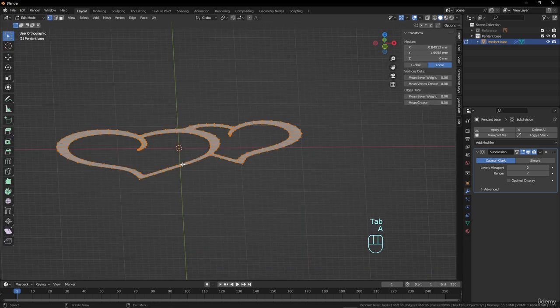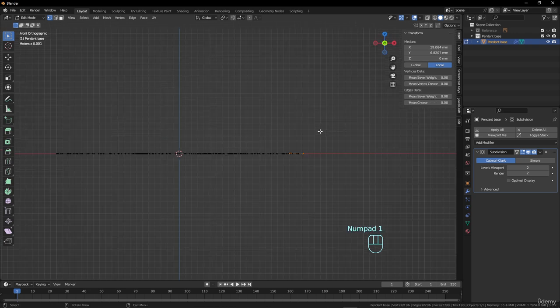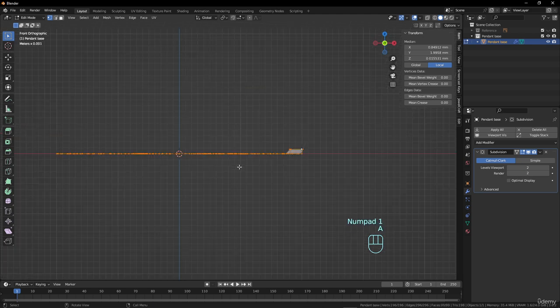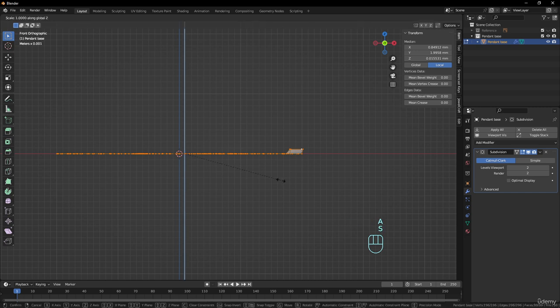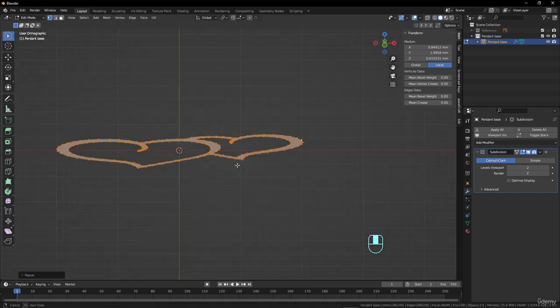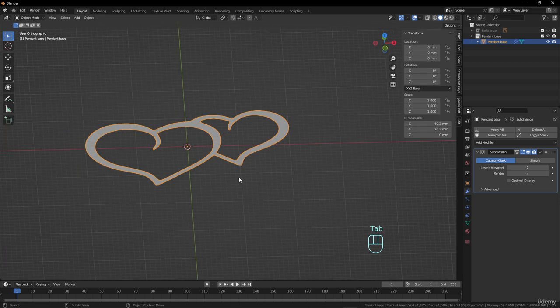If it's not flat, if for example there are some vertices there, who knows, and you make a bad extrusion, or you changed the view during the process of extruding, you'll have something like this. When you have this kind of problem, you press S Z 0 like that, and everything will be flat again. Okay, so now you have a design that is ready to extrude.